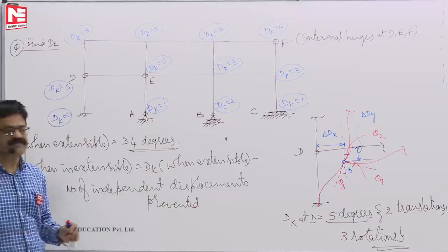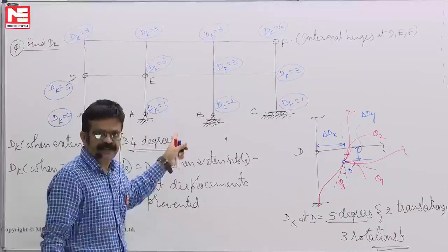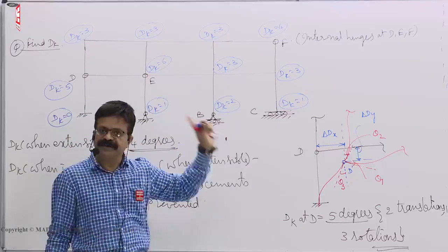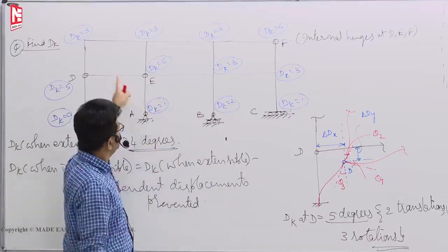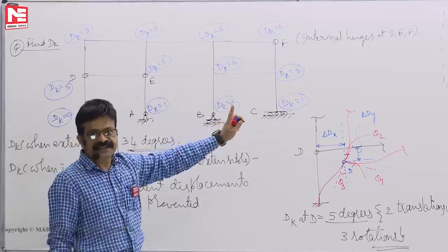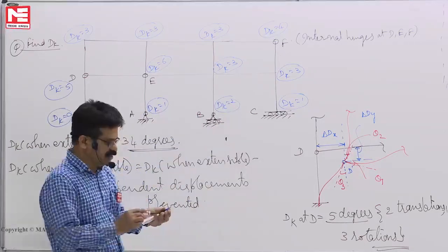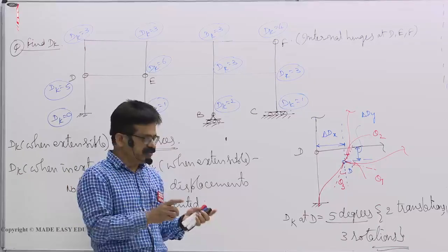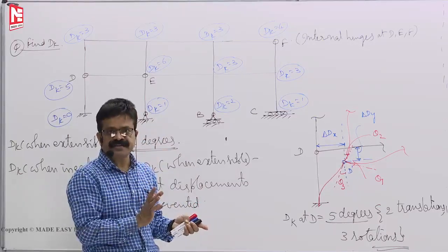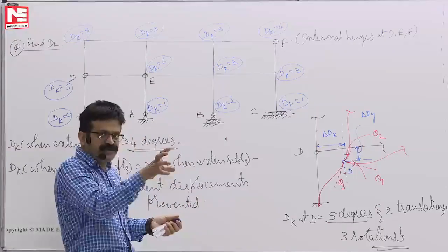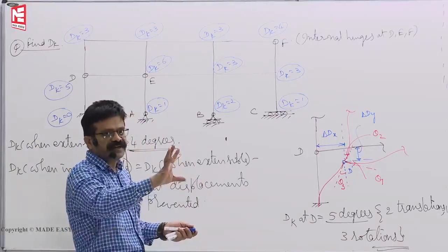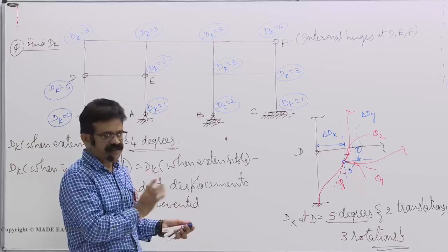Such structures where there is no bracing, all displacements are independent displacements. If you count the number of axially rigid members, so many you can subtract easily. That you can do when bracing is not done. All displacements are independent. That means no compatibility relations; members can elongate or contract independent of the other.